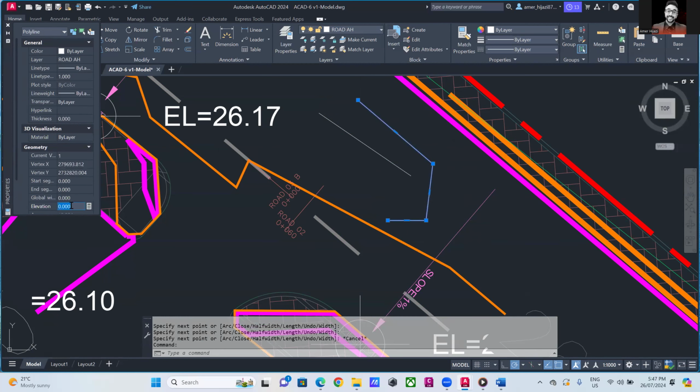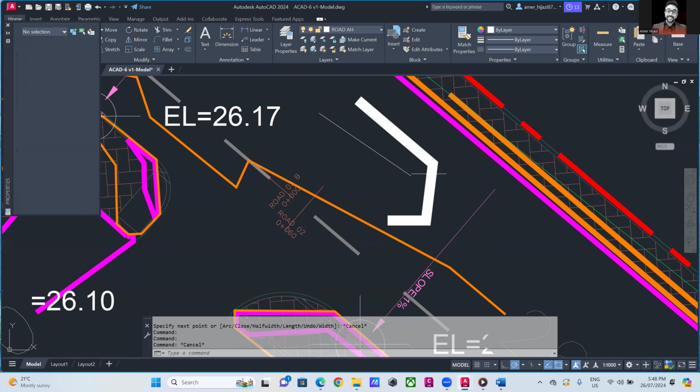You are actually able to add the elevation. You can also add the width. For example, we'll make it like this, and see. So it's different if you deal with a line and a polyline. If we need to add properties to the line, like the elevation, it's usually better to use a polyline, even when trying to join different lines.